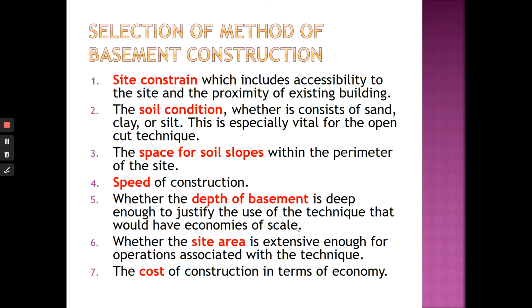Okay, we have learned about cohesive and non-cohesive soil. If it's cohesive soil, open cut might be okay because it's cohesive, sticky. But if it's non-cohesive, for example sand, if you do open cut, especially the stiff one, when the degree is more than 70, then you need to cover it up. Cut and cover probably is suitable. The third one, space for soil slopes. If you don't have space, how do you want to do the slopes? So you can't actually use open cut anymore.